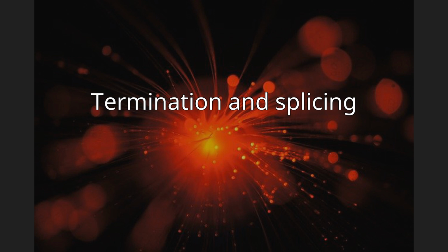A typical connector is installed by preparing the fiber end and inserting it into the rear of the connector body. Quick-set adhesive is usually used to hold the fiber securely, and a strain relief is secured to the rear. Once the adhesive sets, the fiber's end is polished to a mirror finish. Various polish profiles are used depending on the type of fiber and the application.